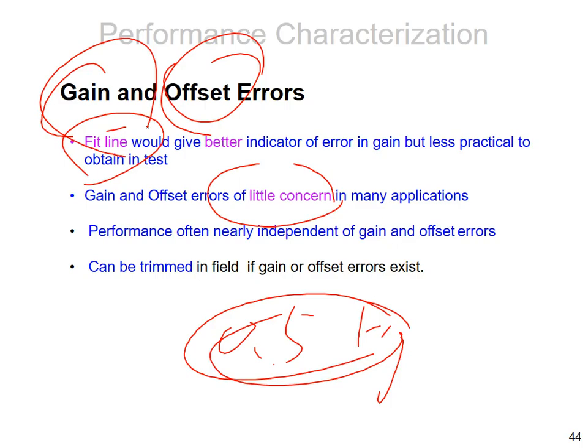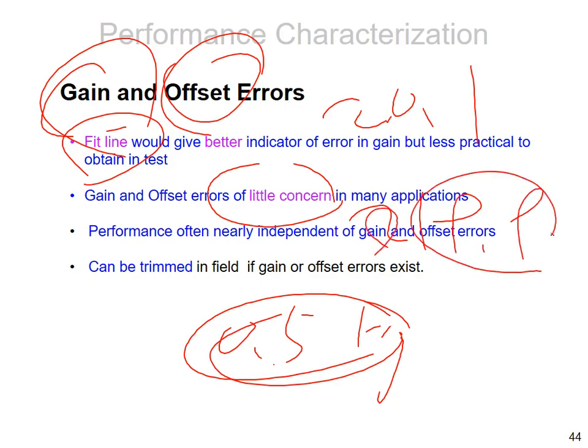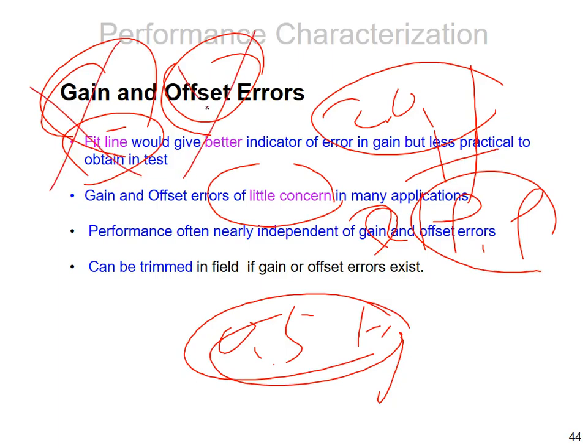No, only if the quality is good enough. For example, for the first mobile phone, the ENOB is 20.1, for the second one it is 19.9. They are not the same, but the quality to human ears is about the same. Who cares? Anyway, gain error and offset error usually are not important.